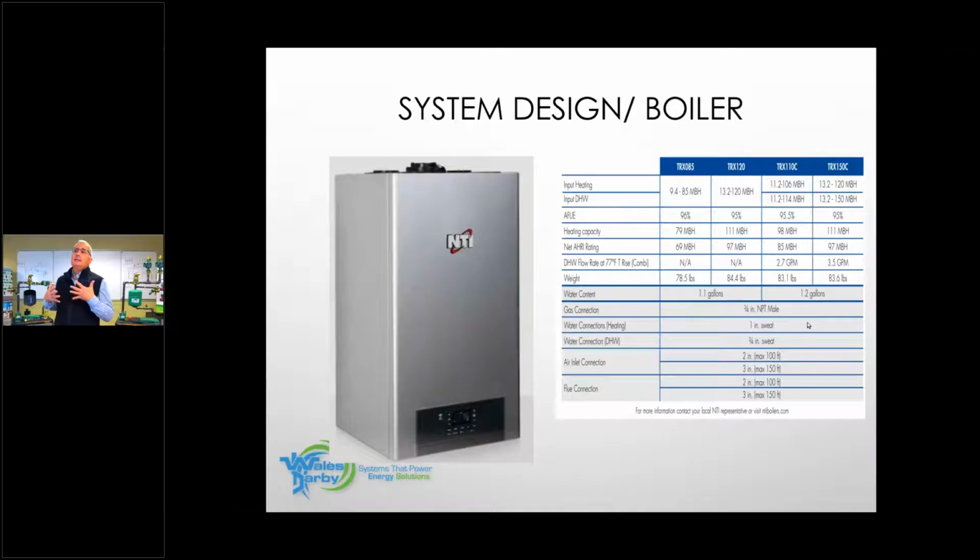So the boiler can sense outdoor temperature either with a sensor or via the web on internet weather. So you can run this boiler 2 ways. I can either follow the weather by the internet or sense outside temperature with a sensor. If I go with the internet, no need to run an outdoor sensor. So this means my boiler is going to adjust as the temperature outside changes, which is a big deal because